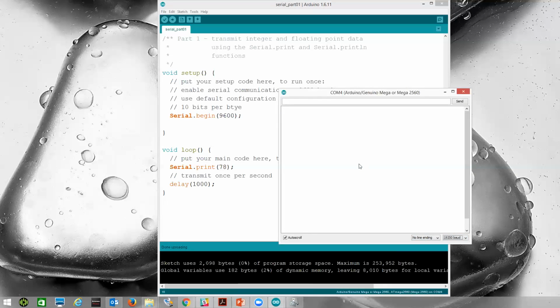So if I select a different baud rate here, it restarts the program, and instead of seeing a 7 and an 8, I see a tilde, and it looks like a 0 or a phi, perhaps. So what's happening is when I do this, over here, this is transmitting 7 and 8, but it's transmitting at 9600 baud. 19.2 is twice 9600. This is sampling at twice the rate this is transmitting. And because these two are working with different clocks, different baud rates, then this is sampling more often, and it's not giving us the same data, right? It looks like we have corrupted data.